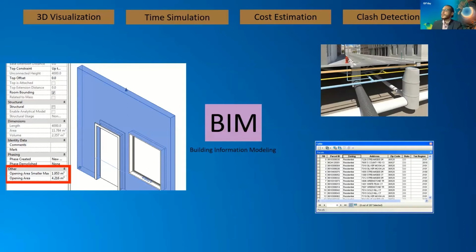It can happen if you have multiple utility networks underground, and for example, an electrical trench will be intersected with a water pipeline. So you have to stop the project and wait for the final decision. All of this won't happen if you have an aggregate BIM model that contains all of the disciplines in one central model to have a clash detection before you go to the next phase of the construction.